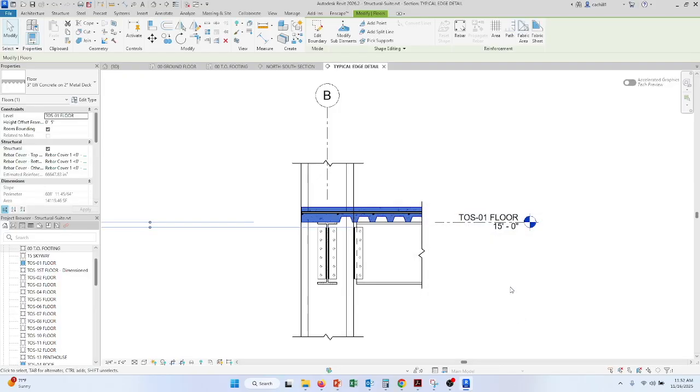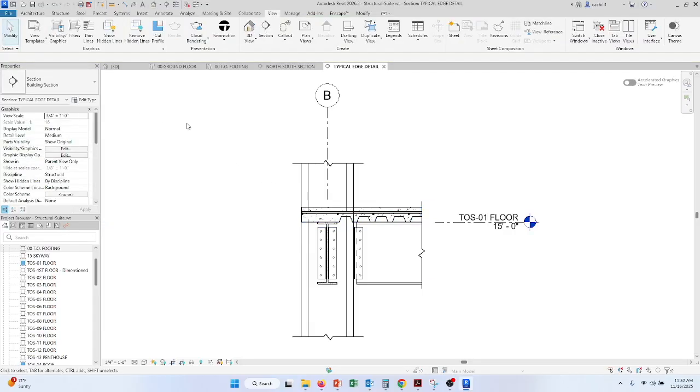End the command by using any one of the following. In any tab on the ribbon, click Modify. Press Escape once or twice to revert to Modify. Right-click and select Cancel once or twice, or start another command.